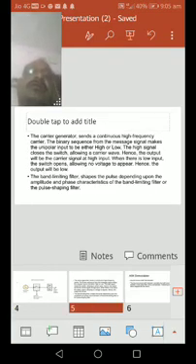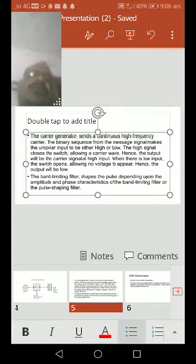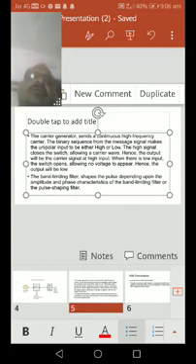The carrier generator sends a continuous high frequency carrier signal. The binary sequence from the message signal makes the unipolar input either high or low. The high level signal closes the switch, so the output will be the carrier signal at a high input. When there is a low input, the switch is open. Switch on means transmitting a one bit; switch off means the carrier is not allowed through, so no voltage appears and the output will be low.